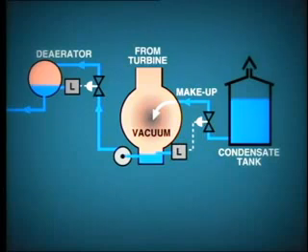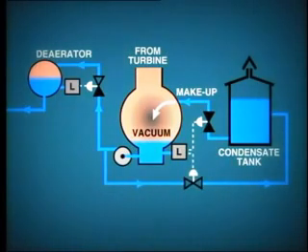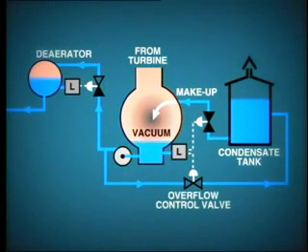When load is increased, the opposite situation takes place, as the boiler water level increases due to swell. In this case, the boiler feed water control valve reduces flow, the de-aerator level tends to rise, so decreasing the de-aerator control valve opening. This causes the hot well level to rise, thus causing the makeup valve to close completely. If the hot well level continues to rise, we must find some means of dumping this excess condensate back to the condensate tank. This is achieved by fitting a connection from the condensate system through a control valve back to the condensate tank. This is known as the overflow control valve, and its opening is determined by high water level in the condenser hot well.